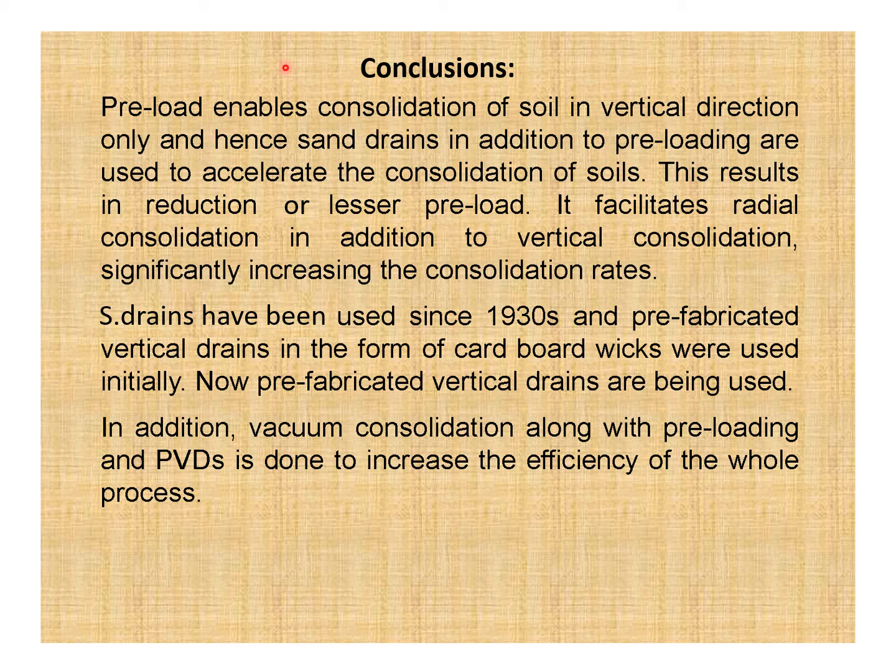Now the slide for conclusions. Preload enables consolidation of soil in the vertical direction only. And hence sand drains, in addition to preloading, are used to accelerate the consolidation of soils. This results in reduction or lesser preload. It facilitates radial consolidation in addition to vertical consolidation, significantly increasing the consolidation rates.